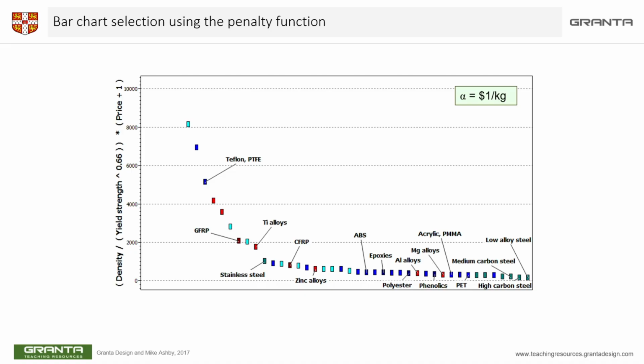And maybe, for example, certain limits would have already been prescribed, like fracture toughness. There should be a minimum benchmark. You don't want very brittle materials to appear in this selection. Manufacturability into that shape, so moldability, can also be applied using the tree control in CES. So those options would have already been applied at this stage. So now the graph that I'm showing you basically has this value, not 10, rather it is 1, okay?